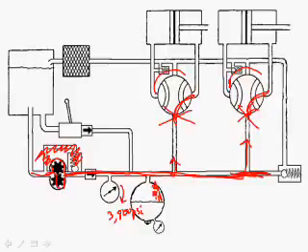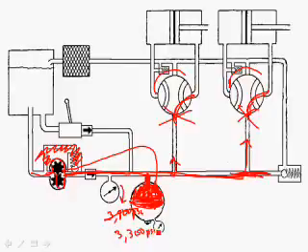Well, if we had the accumulator in here, some of this fluid coming out of the pump could go into the accumulator. Now this diaphragm would move over, and we'd have more than this half full of hydraulic fluid. But then the pressure, instead of going up to 3800, it might only go up to 3300 psi.